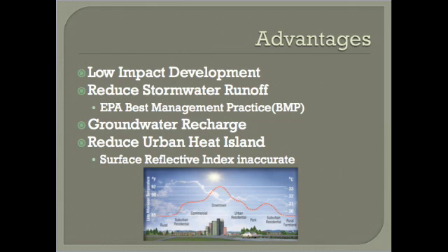Pervious concrete is the EPA's new best management practice for managing stormwater. Pervious concrete offers the same ideas as a detention basin, holding the water and recharging the natural aquifer. As we talked of earlier, pervious also reduces the urban heat island. Pervious reduces the urban heat island because its open pore structure naturally stays cooler and absorbs less heat.